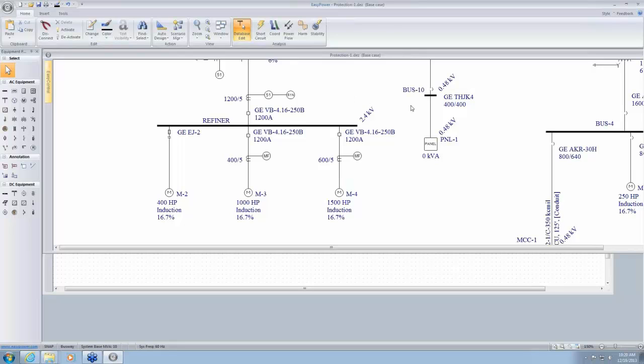When the IEEE 1584 committee did some tests back in 2002 or prior to that, the lab had this electrode or conductor configuration such that the conductor was in a vertical position, and the source was connected towards the top of the conductors, and the arc was facing downwards.